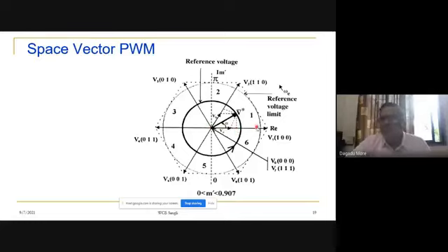And here we have seen that in the case of the 180 degrees mode, our space vector is jumping from one place to another. From V1, it jumps to V2, it does not move. Similarly, it stays here for a 60 degrees duration, or 3.3 milliseconds, and then switches to the other. So the space vector is jumping from one position to another. It is not moving at a constant speed. That's why with the 180 degrees mode of conduction we have a quasi-square output voltage waveform, and because of that we have a THD of almost 30%, 31%. That we don't want.